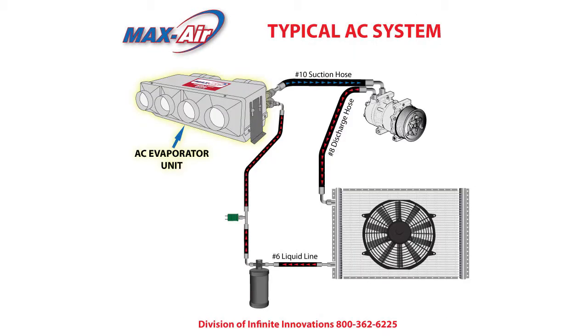the airflow. As the refrigerant goes through the expansion valve, it turns into a low-pressure gas and rapidly cools the evaporator coil inside the AC unit case. The fan mounted on the evaporator case has inlets that pull the warm air out of the vehicle while blowing cool air through the evaporator coil, cooling the air coming out of your AC vents.